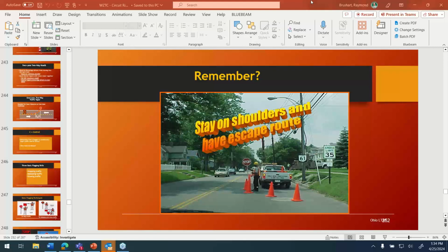But you want those utility poles to be close enough to the edge of pavement that the signs really stand out. It's a judgment call, because if that roadway already has signs on utility poles, then someone must have thought that the utility poles are close enough to motorists as they drive by for them to be effective.